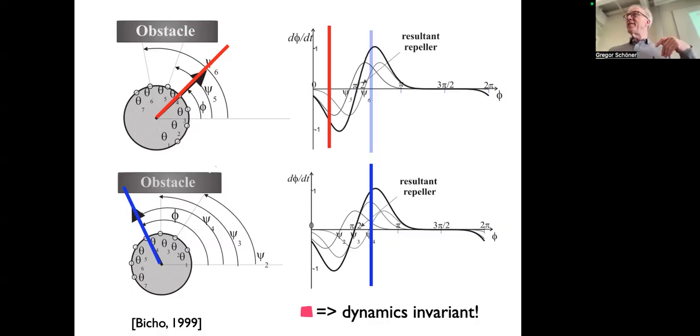And if it's closer than the threshold on the left, I turn right. And it would be rare for the 2 values to be exactly the same. So that is sort of a naive algorithmic analysis, but it's not clear what kind of dynamics that really is. And these vehicles will all end up in corners. They create attractors in corners. You can think through why that's the case.